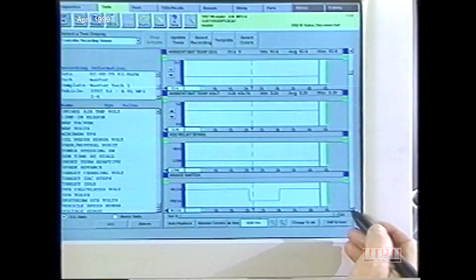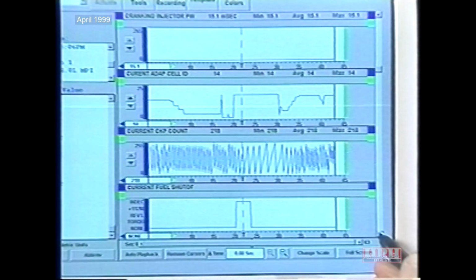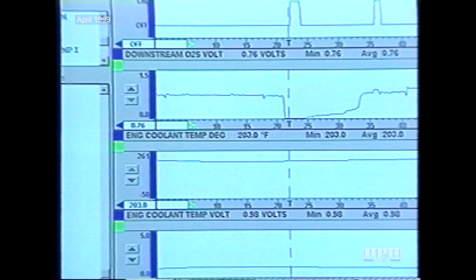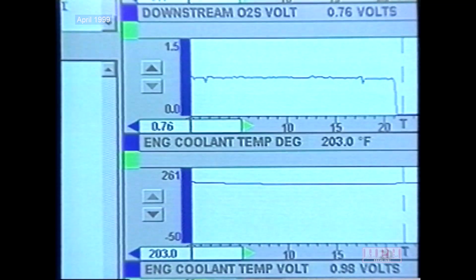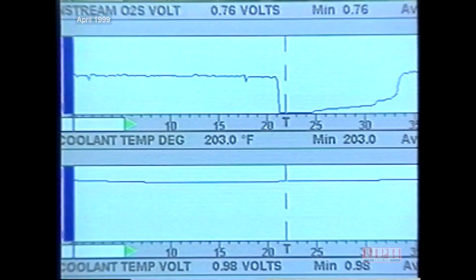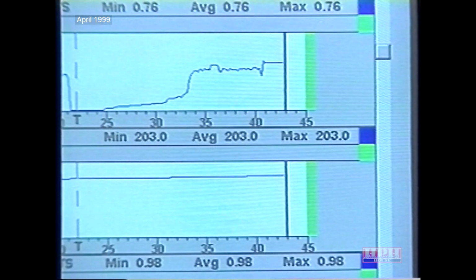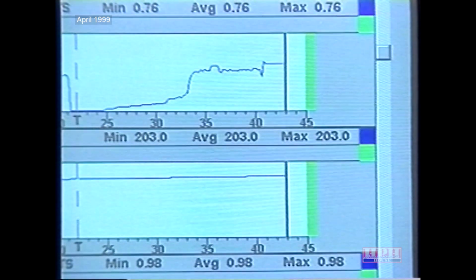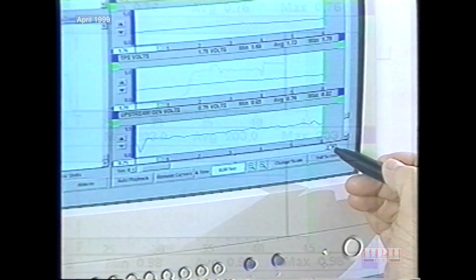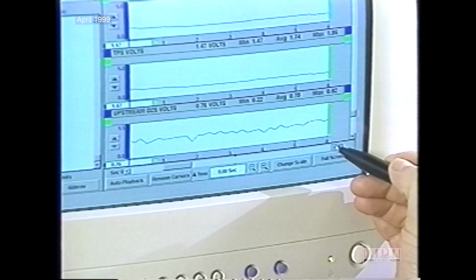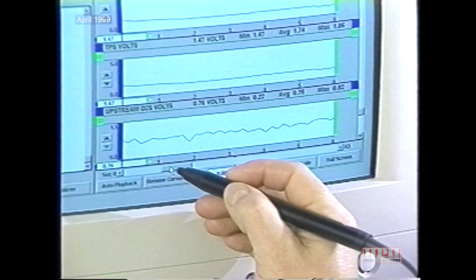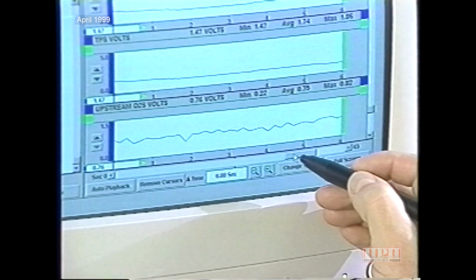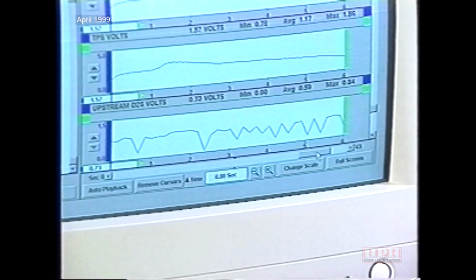The graph of each signal is displayed on the right side of the controller recording viewer screen. Each graph plots the signal value in the appropriate units over time. At the top of each graph, you'll find the signal name along with the current, minimum, average, and maximum values contained within that graph. Beneath the graphs, a slide bar indicates the total time of the recording. Use the arrows or slide bar to display different parts of the graphs.